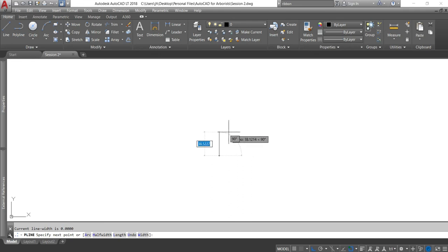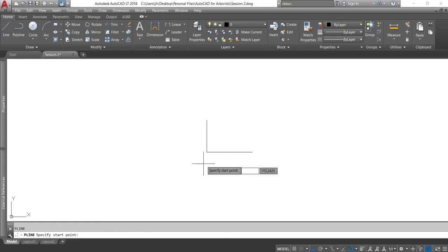crown spreads. So I want to draw a crown spread with north 2 meters. Enter. Zoom in. Draw my second point, snapping onto the end of that bottom line. Come out. This is 3 meters to the east. Hit enter. Enter again to draw another line. Snap onto the end of that line again. Now my south spread might be 6 meters. Hit enter. Enter to complete the line.